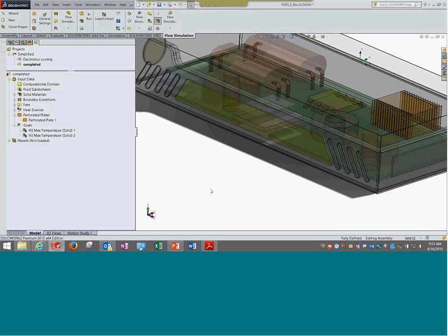In this case, the fan is blowing, probably the air is flowing out through this perforated plate. Actually I have two options. One is the perforated plate and one is the porous media, which we'll discuss later. For all practical purposes, theoretically, it is permitted to do so in certain cases. Obviously, if there are a huge number of holes, we cannot simulate all the holes, and perforated plate is a fair option to use. Saying that, remember, in simple words, what it is creating is a simple pressure drop or resistance to flow. That's it, nothing much.